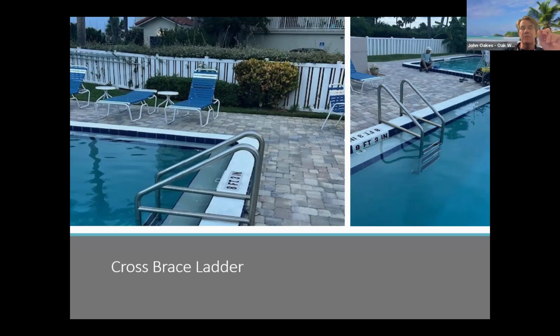It has to be within 1/4 of an inch of elevation all the way around the pool on that front edge. And then there has to be 2 inches of slope from the front edge to the back where the drains are. That's something the health department typically measures after a renovation before they let you open the pool. So it's critical that whomever you hire to do this work is fully aware of what the requirements are going to be to get your pool open.